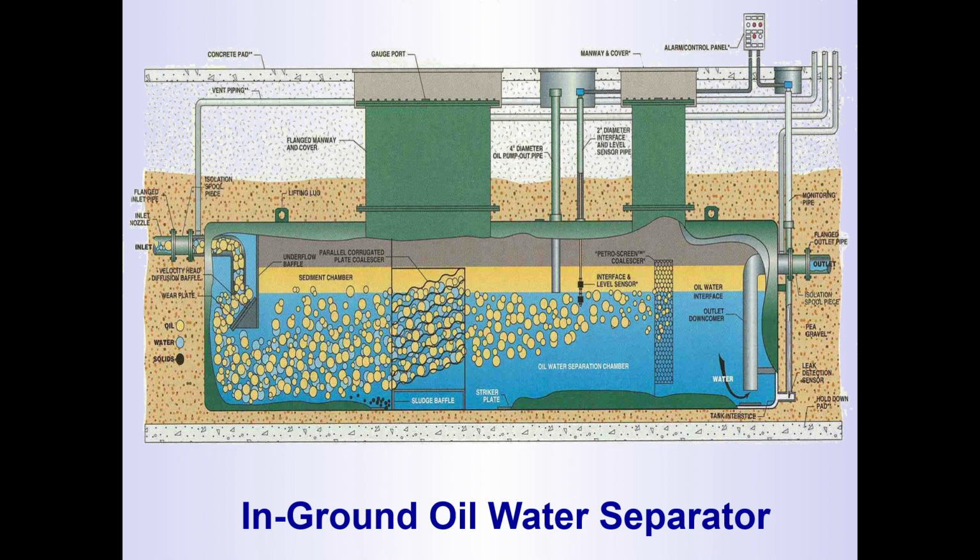Please, you see the diagram. You can see that heavier solids will be sludgy, everything will be settling on the bottom, while the oil will be rising. The same gravity principle applies. Normally we have two different models: gravimetric or parallel plates, and the American Petroleum Institute type. Okay, this will be used for separating oils from industrial wastewater, process wastewater, etc.